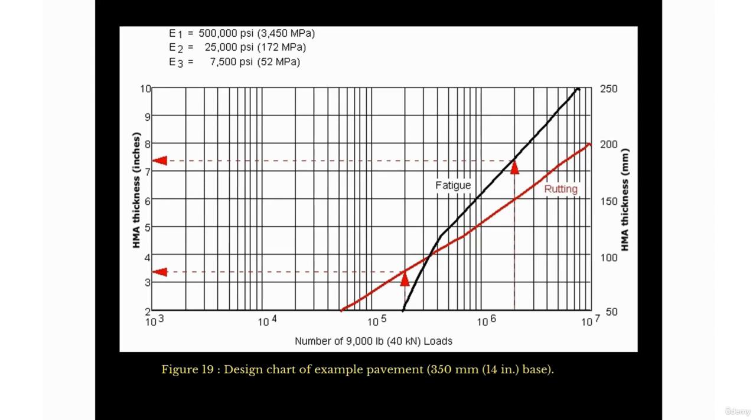And you see for different values here, the 7,500 E3 does not even apply anymore. We're only applying E1 and E2. Those are the only two compression strengths, or forces, in terms of pressure, the PSIs, or the loads, that we would be worried about, and you won't even get fatigue. There will be no fatigue. You might only start to get rutting, but it's minimal.